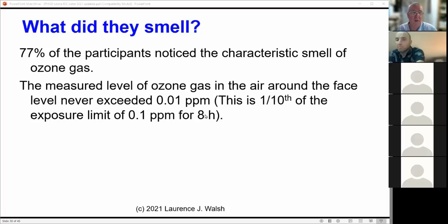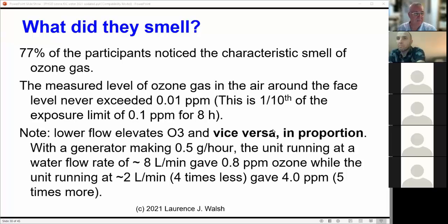And in my former life as a farmer and working in engineering shops, basically doing welding all day, I can tell you from first-hand experience, you get a pretty good exposure to ozone, and that's where this level of 0.1 ppm actually comes from. It's an occupational health and safety level. So the reason I'm telling you that is that the transient smell that you get from the ozonated water, which lasts for a few seconds, is trivial. It has no problems associated with it from a workplace health and safety perspective.